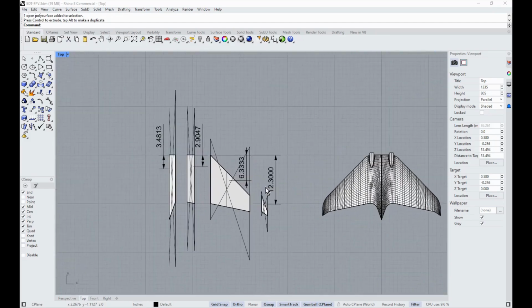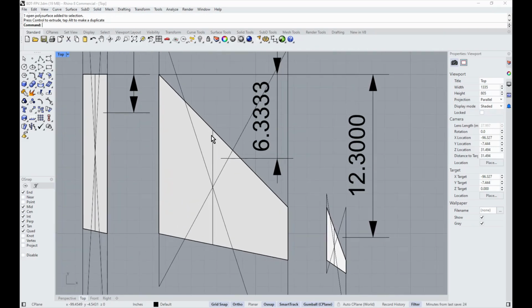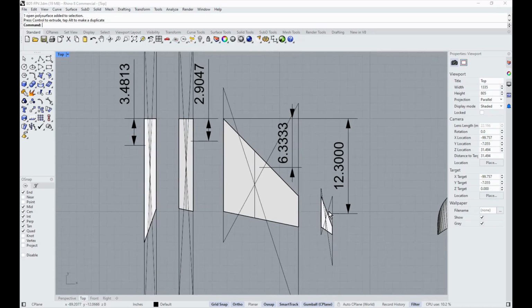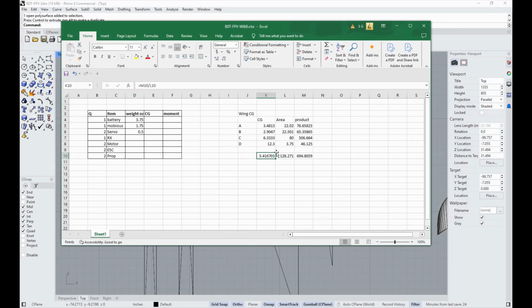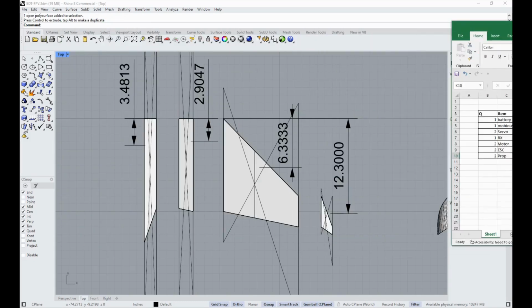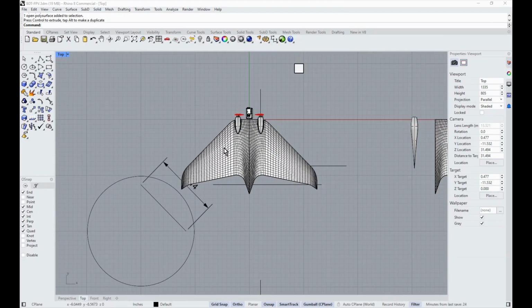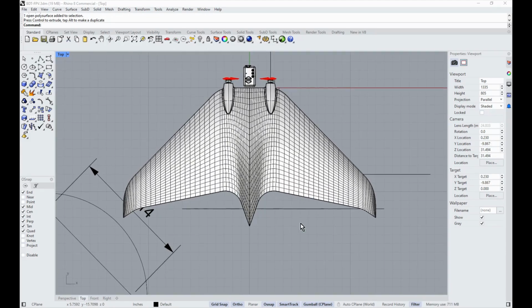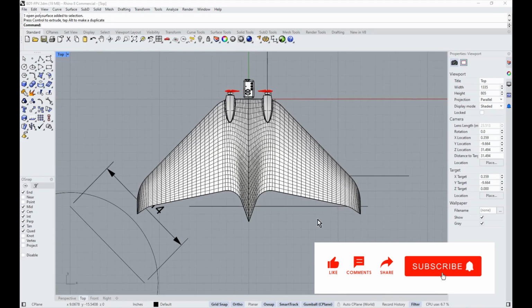And getting back into it, you just take your trapezoided section, you do geometry as shown, and that'll give you the mean aerodynamic chord. And 25% of that chord on a flying wing, if that was just it right there, would be where that CG is. But we have these other sections, and when you do all this math on it, it gives you basically where 25% of the theoretical MAC is. And for a flying wing, that is basically your starting point for a CG. And this is a symmetric airfoil, so it really is a number that's worked for a variety of flying wings and delta wings I've done so far, or even ones I've built from plans.